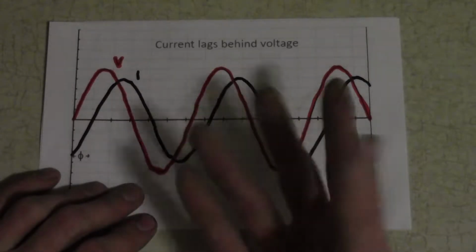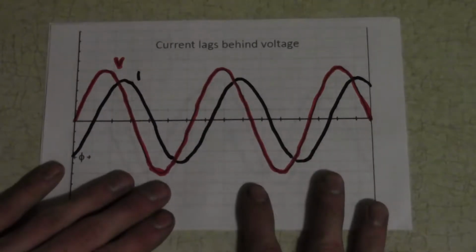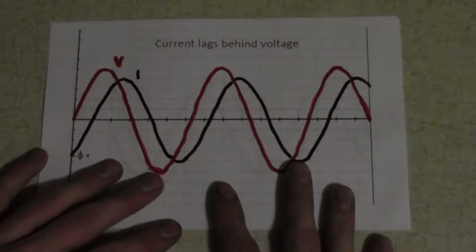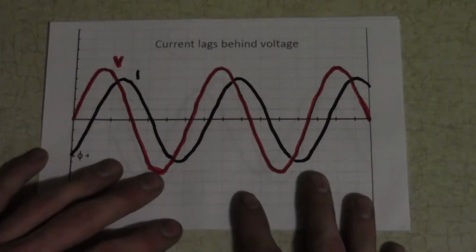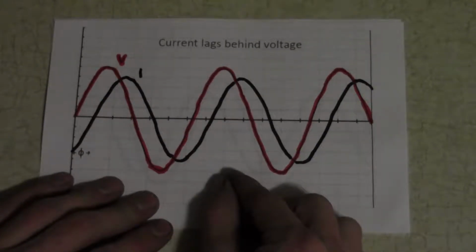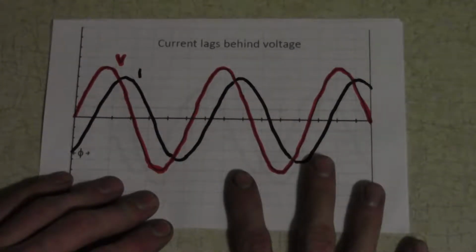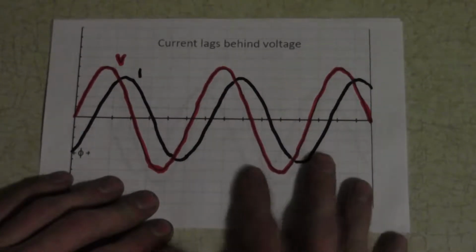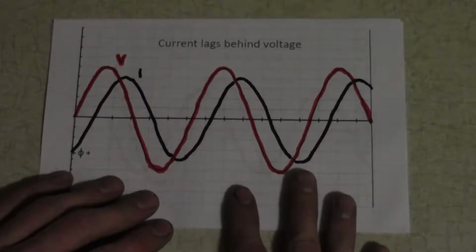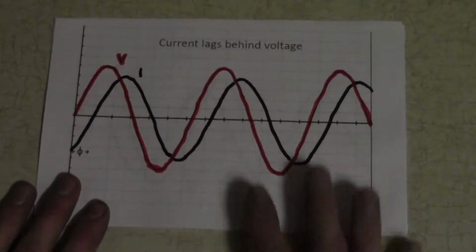And the second reason a general Joe Blow in his garage doesn't care is because, generally speaking, consumer appliances come with their power factor corrected as is. So if you buy something with a large motor in it, a lot of times it'll come with some sort of capacitor on that motor, if the motor is big enough, if the inductor has a large enough inductance to warrant it. So basically, your appliances are going to be close enough anyway. That's how they're going to come from the manufacturer.